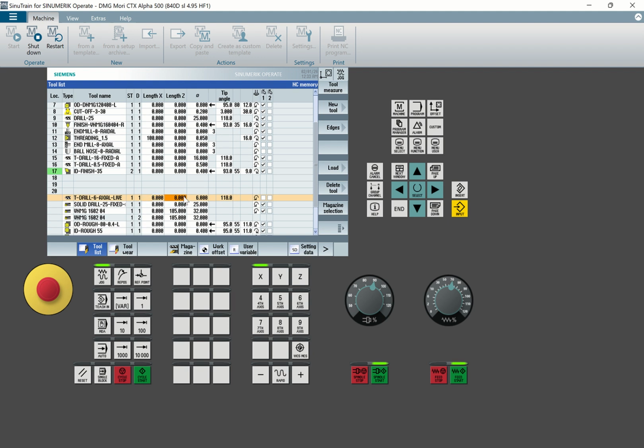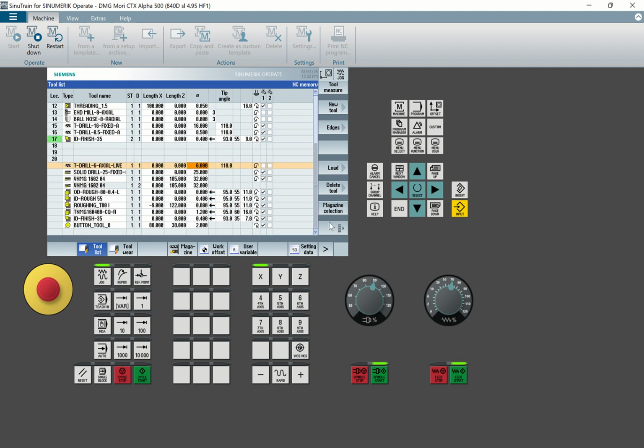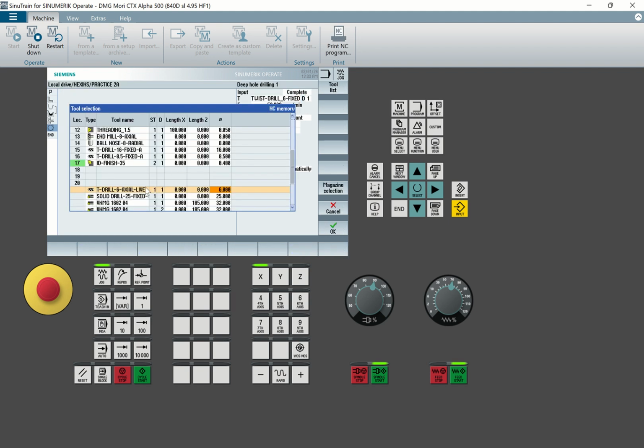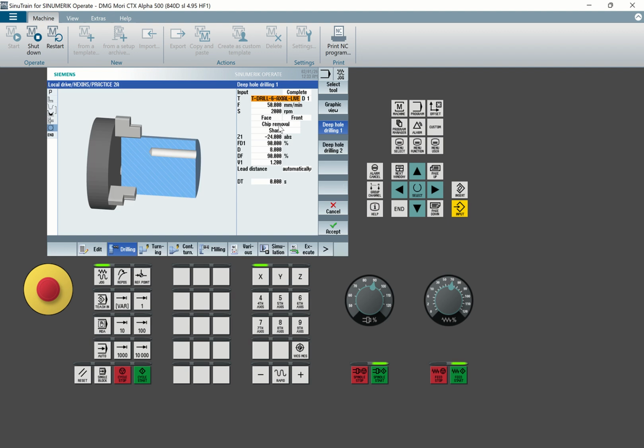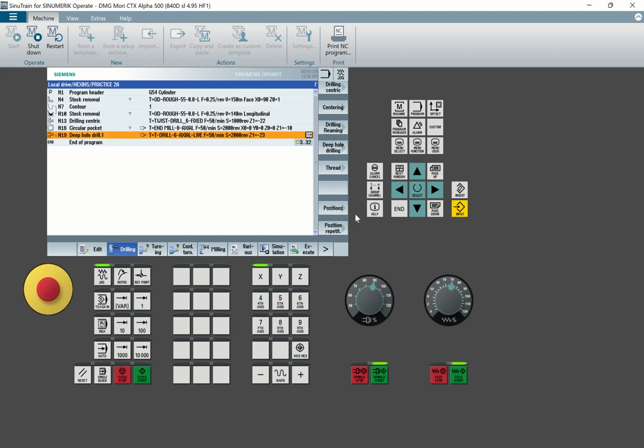Now because you can see the tool now, I can go to program, then I continue to pick my tool as live tool. Okay, chip breaking, I want to use go -20, -23. Okay, using let me use the tip, then accept. From here come to positions.